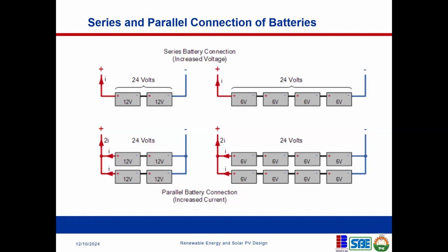So this is just a further illustration of series and parallel. In some cases, you have series and parallel configurations all together. Once you meet your required voltage, every other layer you're going to be adding is going to be in parallel. Once you do your series connection and you meet your required voltage, you're going to keep pairing that series connection if you want to keep increasing the current. And that's what I try to illustrate here.